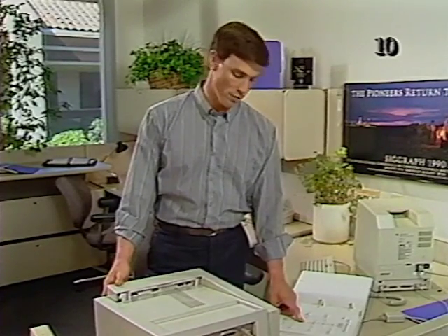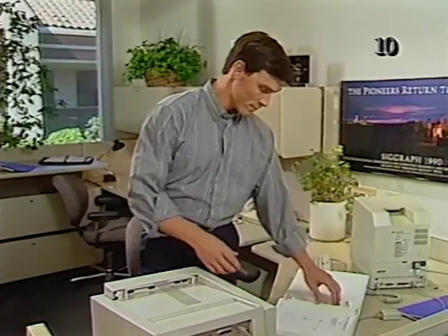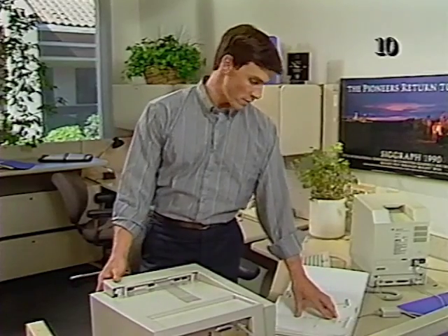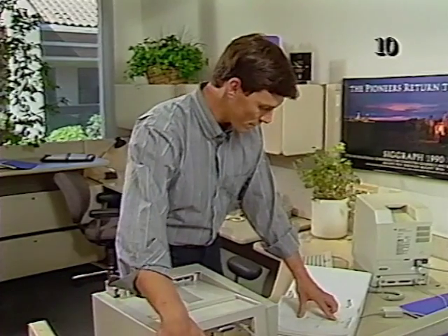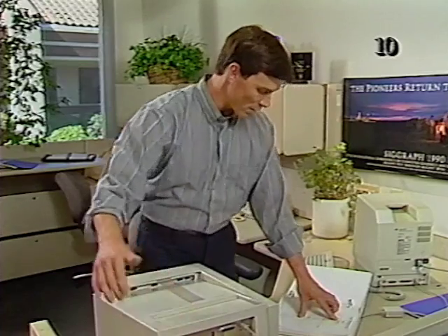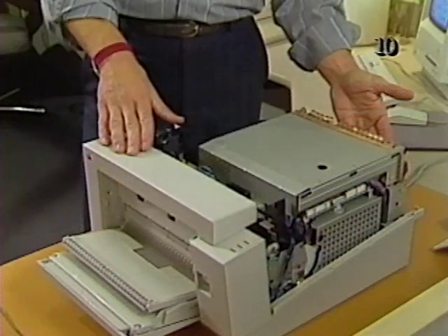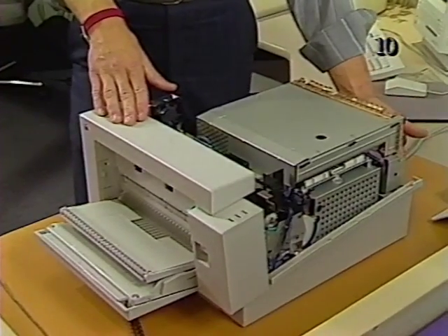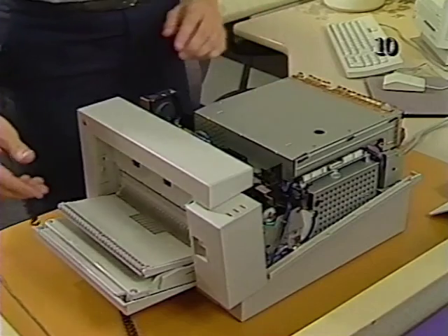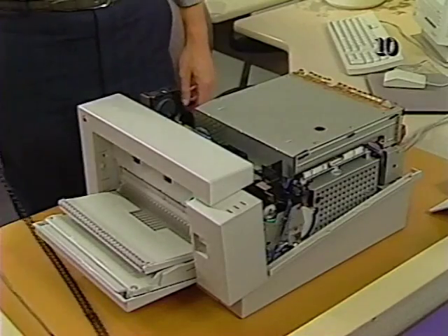The main troubleshooting flowchart refers you to the print engine error flowchart. To check the print engine for errors, power off the printer and wait 3 minutes to reset the error and allow the printer to cool. After removing the top cover and the I/O board, power on the printer. Watch the sides of the front access door. Does the fuser lamp turn on and off? The fuser lamp does turn on and off. What should you do next?